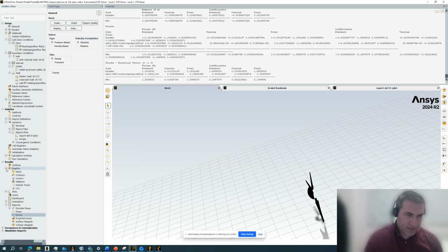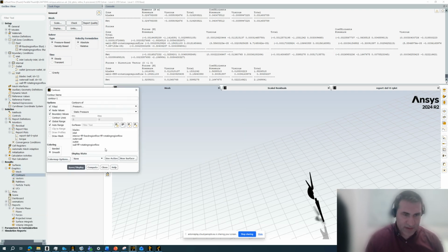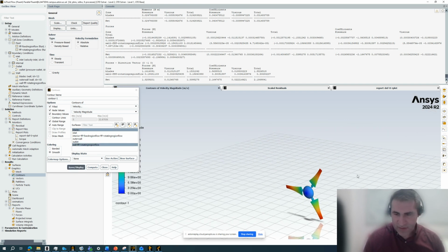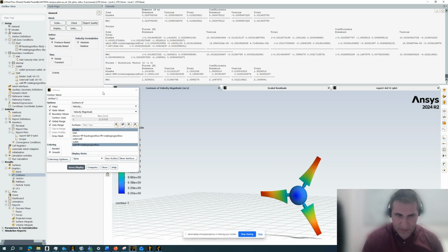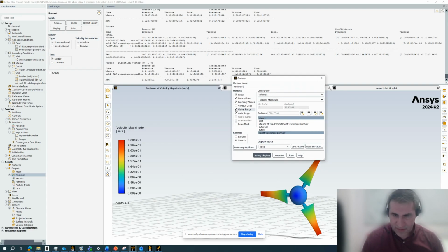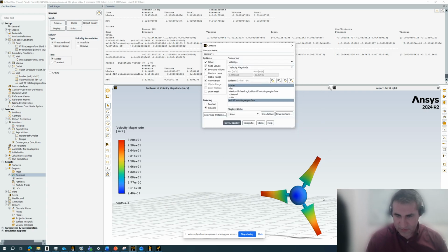Also, I'm interested to see, for example, let's make sure the blades are rotating. If I select the velocity of the blade and select the blade here and nose, perhaps, then I can see here, that's the velocity. Always tick this off, so just remove the tick here, to see only the velocity on the region that we selected, not on the global range.